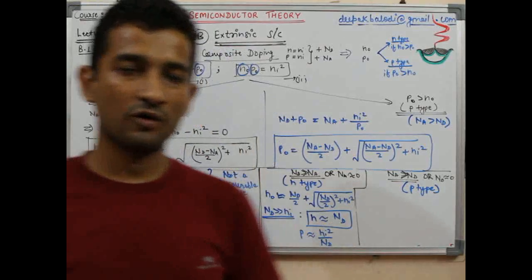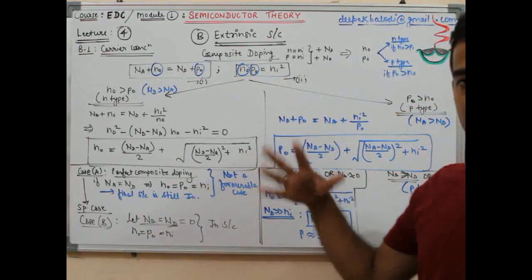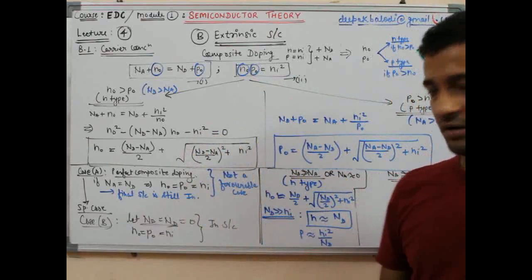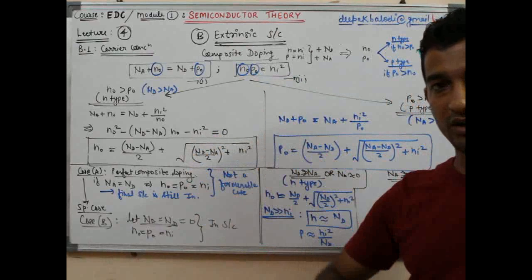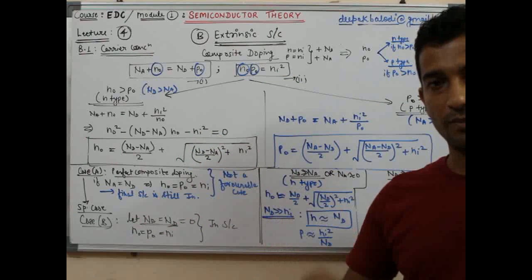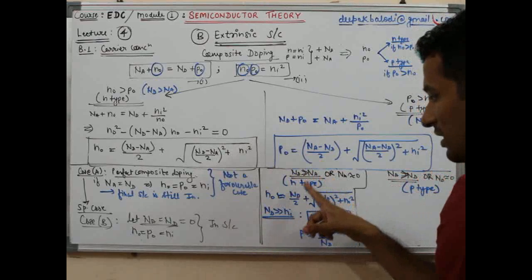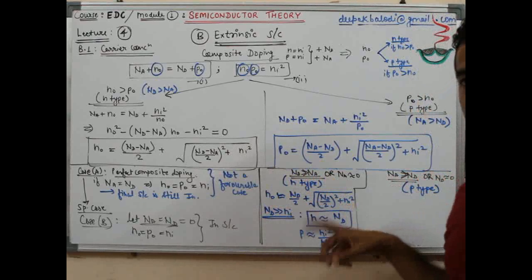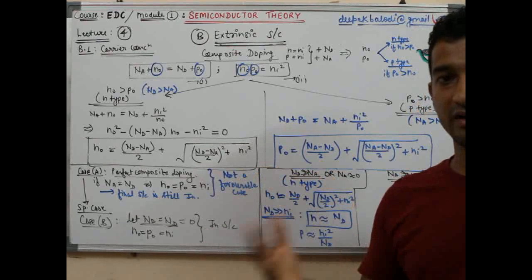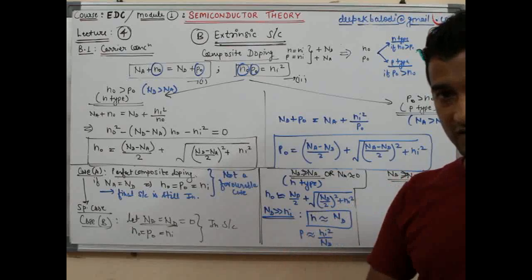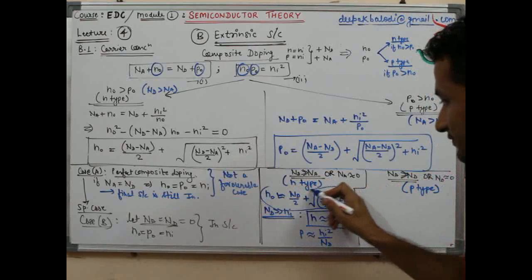So we finally come to the same statement which we argued before this topic, that whenever there is impurity insertion or doping of one type of carriers only with respect to the other, then this is the result. And we also know that we are making some doping concentration which is far greater than Ni. But if it is comparable to Ni, then restrict yourself up to this only.